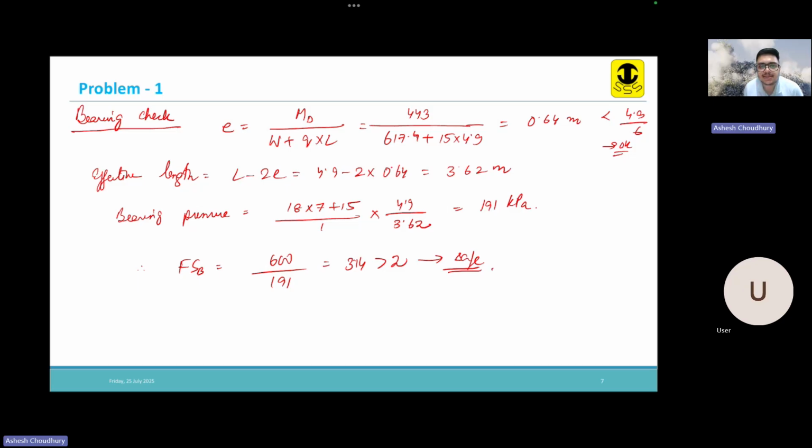Okay. So the external stability analysis is now almost complete. We treated the sliding check, overturning check, and the bearing check. The overall failure check, we don't have the scope to do here, because information is lacking for that in our case. Now next is the internal stability check, right?